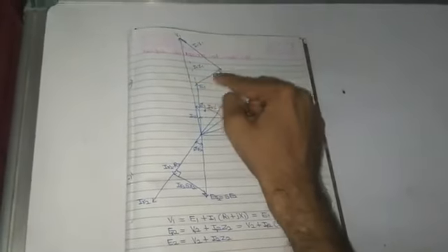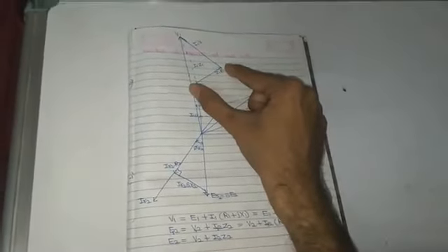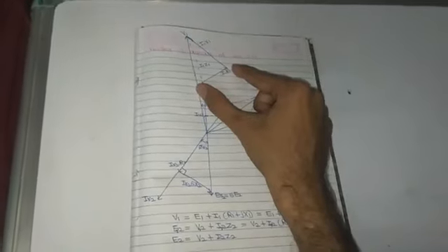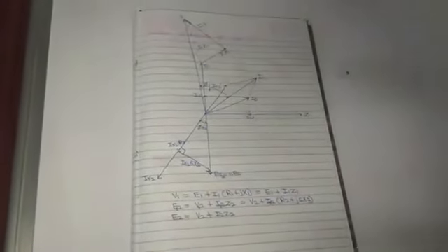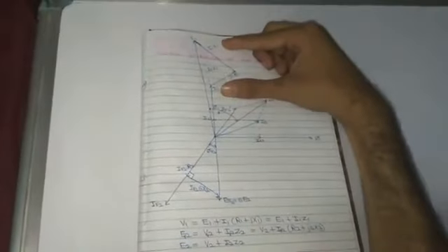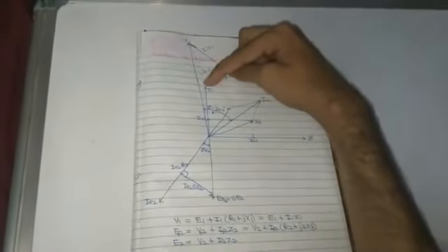I1 X1 is 90 degrees leading to I1 R1. I1 R1 and I1 X1 combine to give I1 Z1, and this is V1, the voltage applied to the stator.